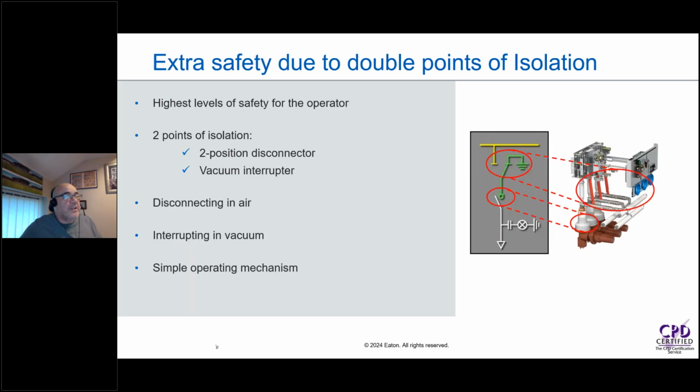One of the other benefits that SF6 free systems give us is we have 2 points of isolation. So here you can see at the bottom where you've got the cable, that denotes the vacuum bottle. That's now in the open position. And then we've also got a second open point from the bus system, where the service selector switch is in the earth position. So if we were to follow this through, the next logical step in this scenario would be to close the vacuum circuit breaker, thus earthing the circuit cable down, or earthing maybe the transformer down.